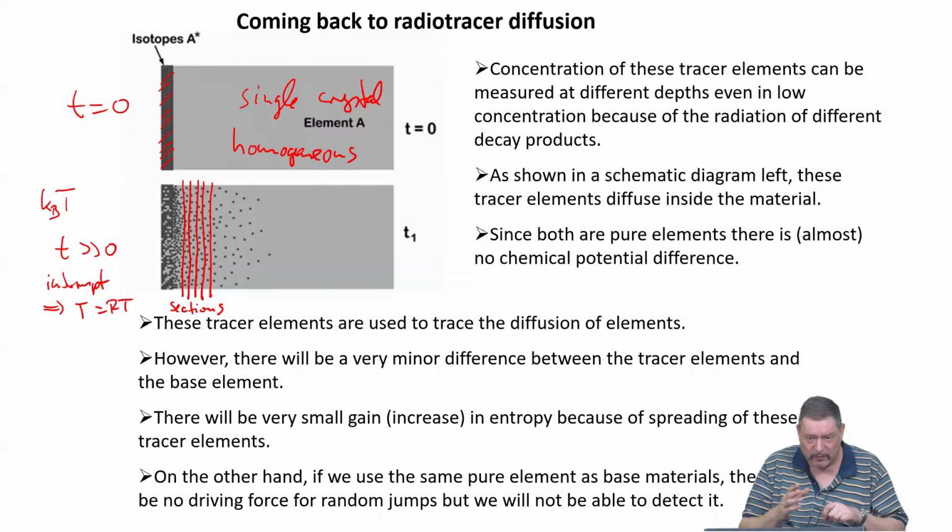So it means that if the diffusion process is very slow, or if you have only a very small number of diffusion channels in your material, still the radio tracer method can give you a result. For example, we are able to measure grain boundary diffusion in a bicrystal. It means you have a huge crystal, two bound together, and there's only one interface.